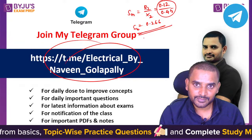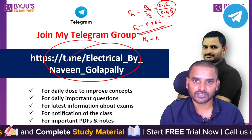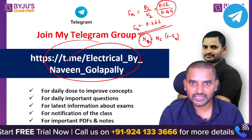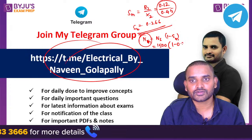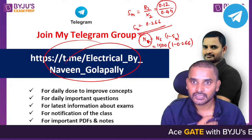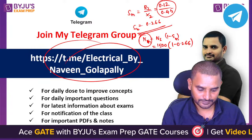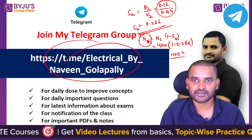Now substitute this slip and you'll get the rotor speed. This is the speed corresponding to maximum torque: 1500 of 1 minus 0.266. I'm getting the speed corresponding to maximum torque as around 1100 RPM.